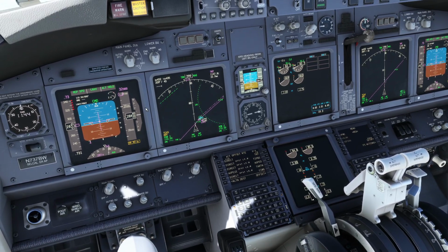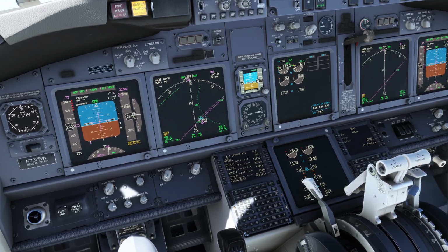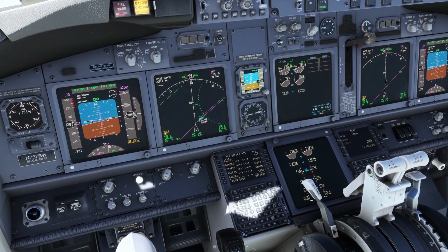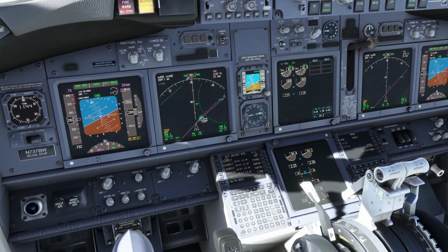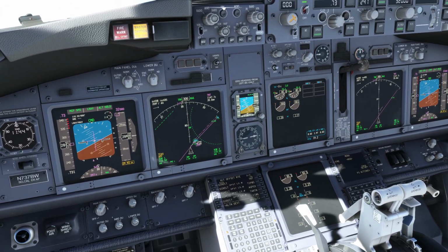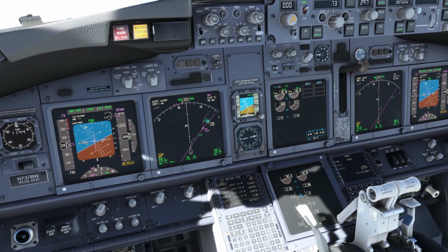So just to go back over what we've looked at today, we've looked at adding and removing waypoints. We've done direct to, we've done vector waypoints, we've done Abeam waypoints, which is really a way of pre-calculating vector waypoints. We've done intercept courses, we've done offset courses. Now the thing that we missed initially when we set the offset course was, let's just zoom that in, that you have to set a start point for it. It won't do it from where you are. You have to say, at what point.